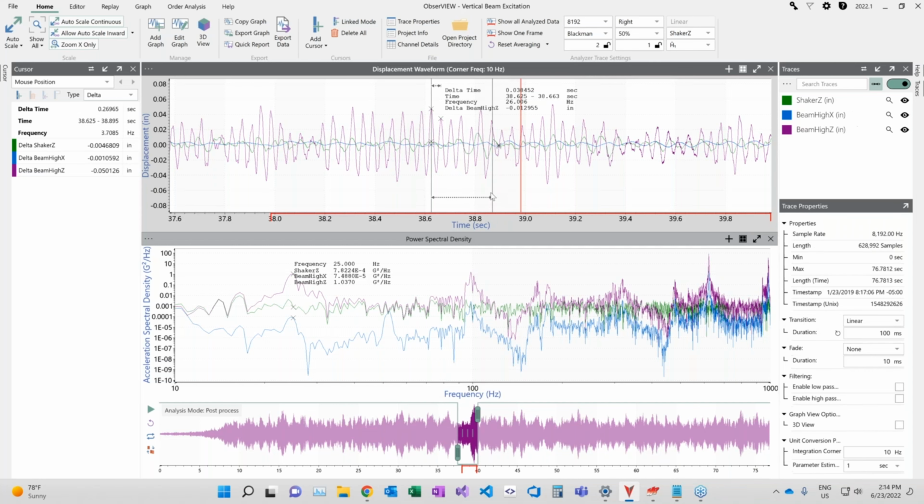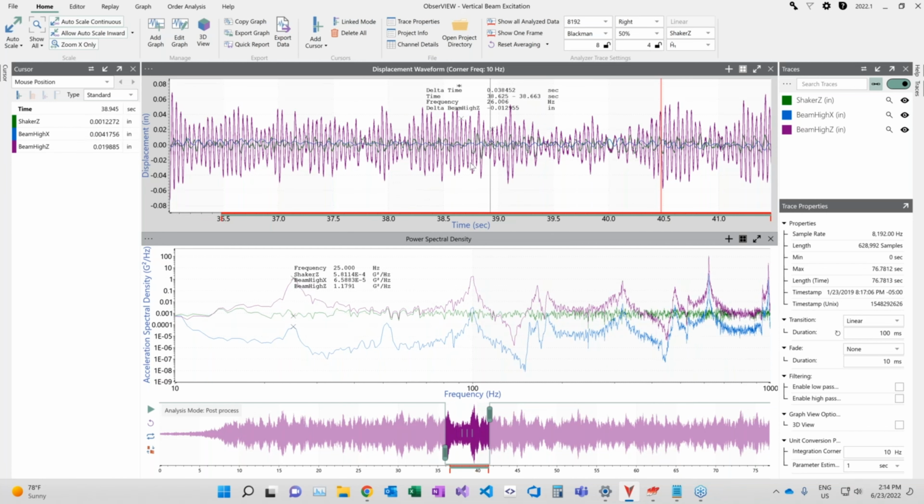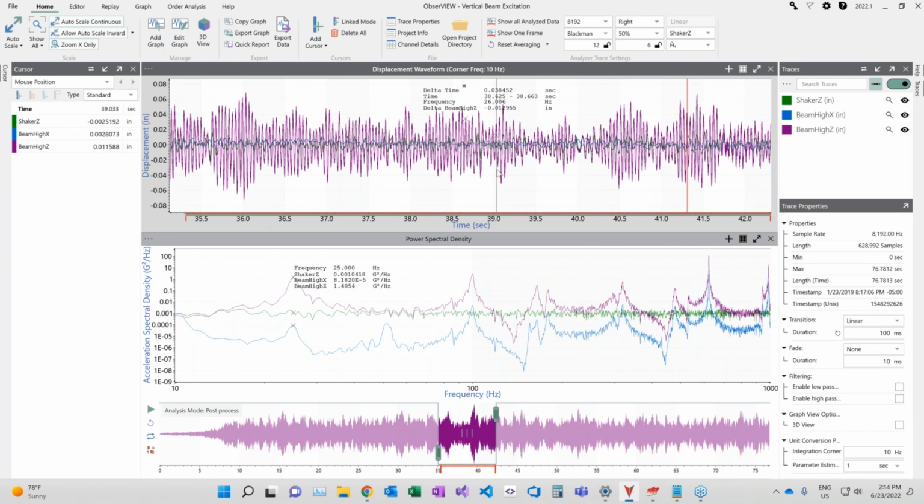So that is the power of using a displacement conversion on time data. It basically will de-emphasize the high frequencies and make it much easier to see low frequency vibration in the time waveform. And this can be helpful for diagnostics and looking at things over time.